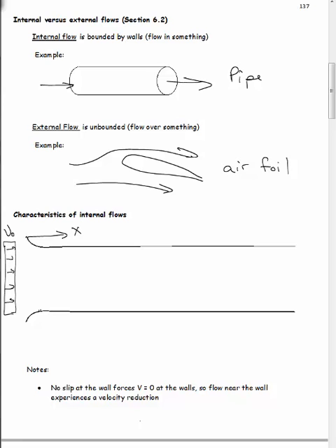Okay, so if you go into this pipe just a little bit, there's going to be a very short area where the velocity is going to go from 0 out to almost this, or actually a little higher than what it is here. And then it's going to do the same thing. This is round, remember. These are not two plates. This is round. So you're going to get a velocity profile that looks something like that. It's flat in the middle, and just the edges are going to decrease down to 0 velocity.